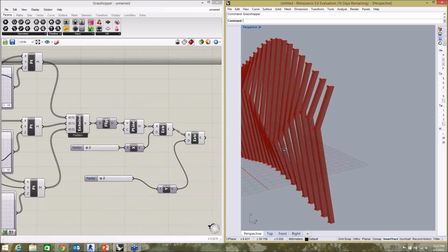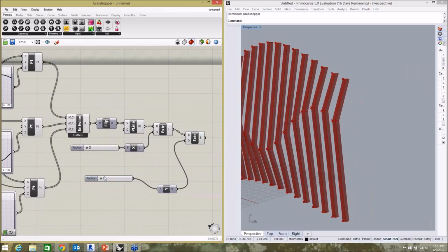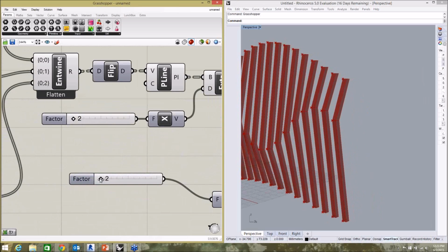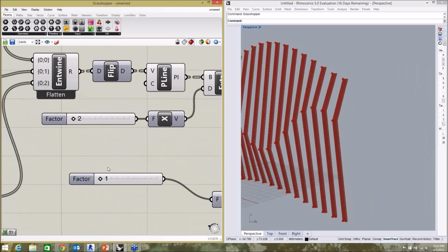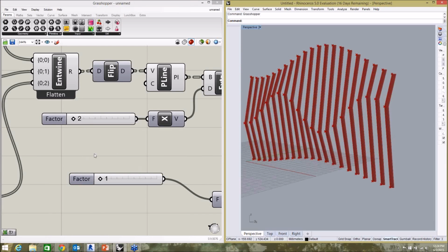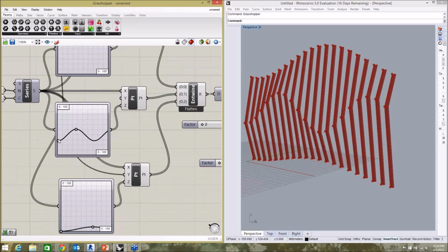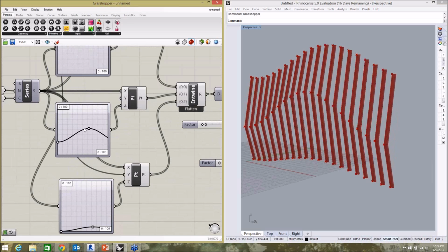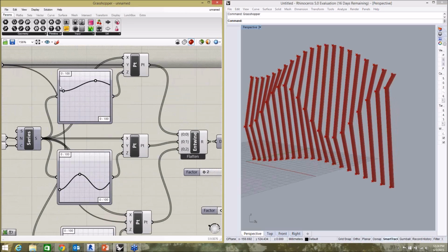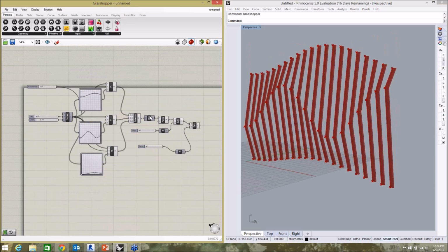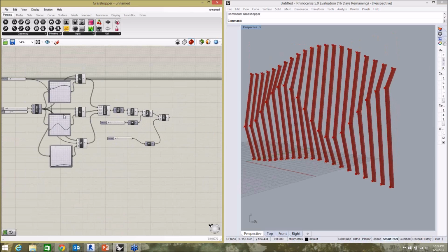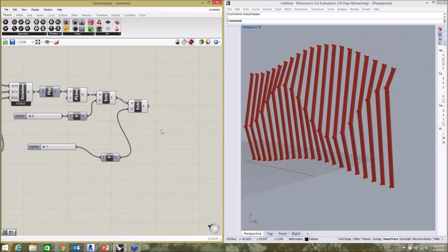And then this could be represented as some tube steel for a rain screen, something like that. But you can see I'm actually able to now parametrically drive that. Okay, really cool facade system going on here. And I can update this. It's updating all of my geometric information. Okay. And so what this allows you to do is to create multiple design iterations. Just in a few minutes here, in a pretty simple script, we have this pretty complex rain screen system.